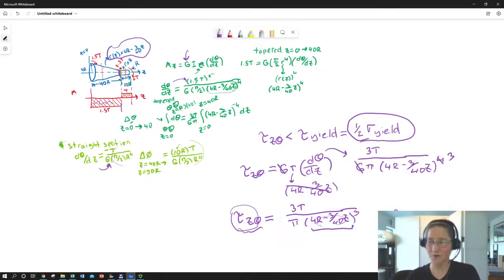if you're adding up your angles of twist, and certainly remember the equations that are specific to any length of the shaft, whether it's because you have a certain radius profile, you have a certain shear modulus, not likely, you have a certain internal moment due to the way you've applied the torques. Those each need to be treated separately to calculate twist rate, to calculate twist, and to calculate max shear. So that is it for this.